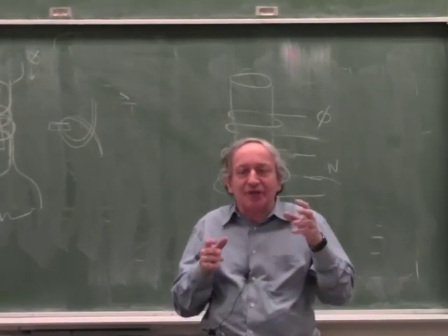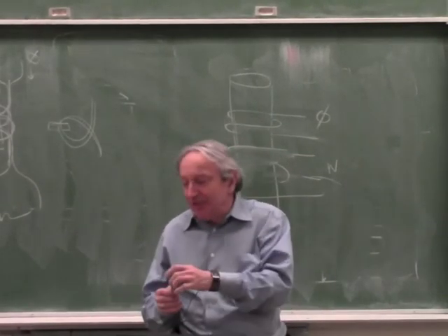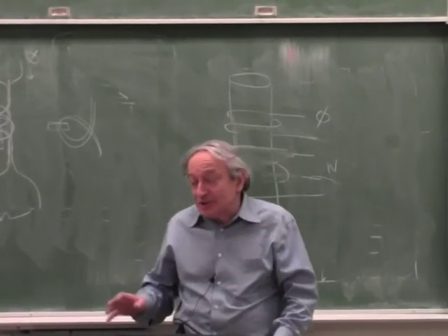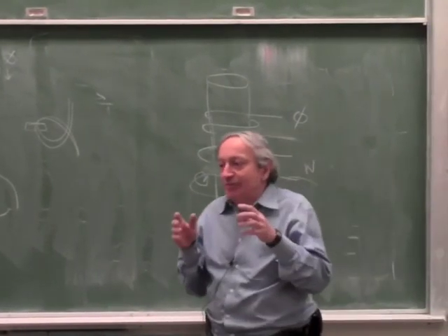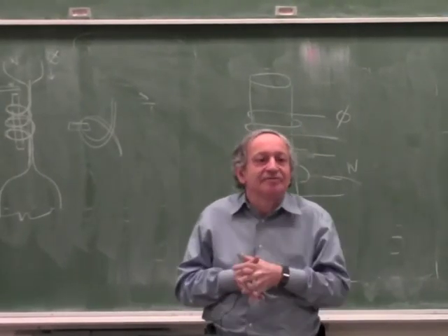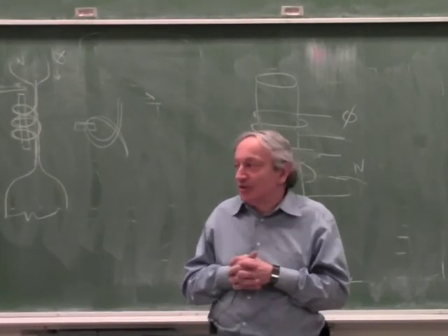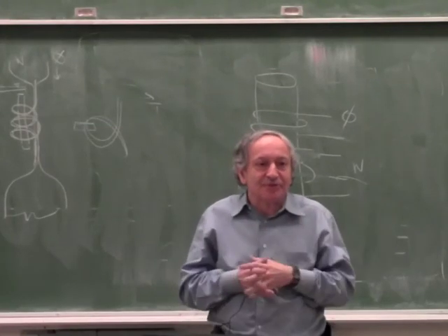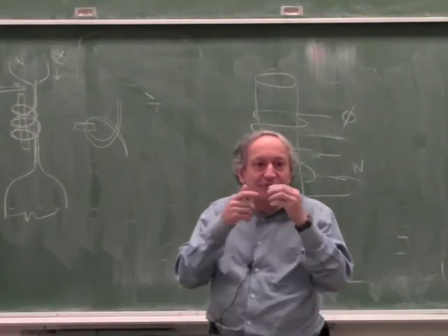If you look at high-end connectors, even a BNC, if you look at the inner pin, it's gold-plated. Any high-end connectors, not just for RF, are gold-plated, but in RF stuff, when you open up high-frequency equipment, everything is silver-plated and gold-plated inside. Yes? Pardon? Okay, number one, corrosion resistance, because gold protects it. What's the second reason? Silver, by the way, is not so good for corrosion, but gold is the best. So number one, corrosion resistance, you want good contact.